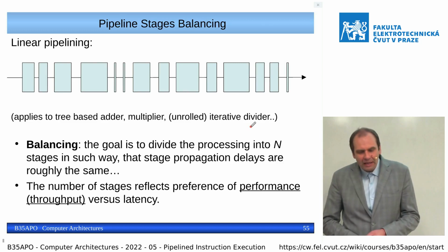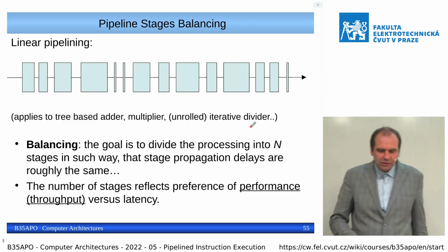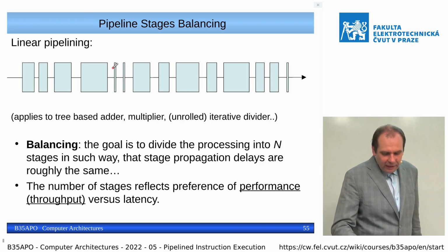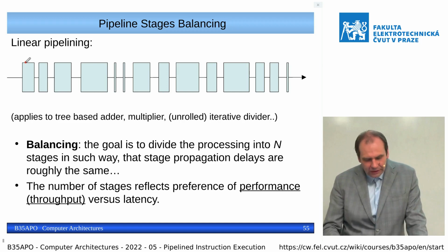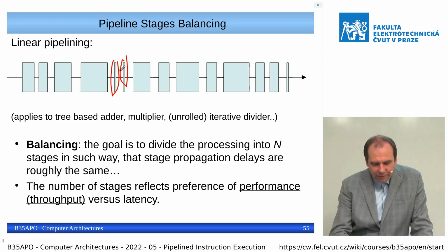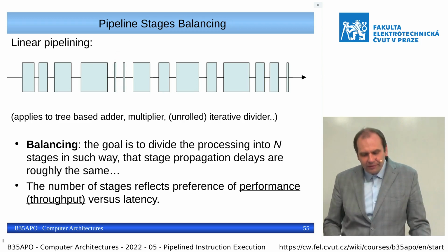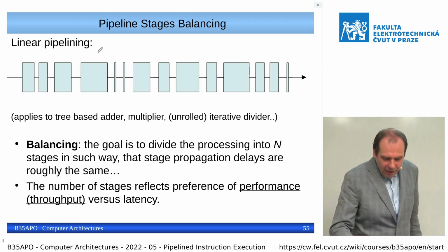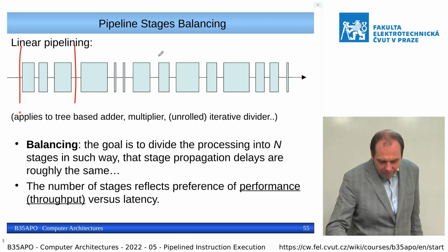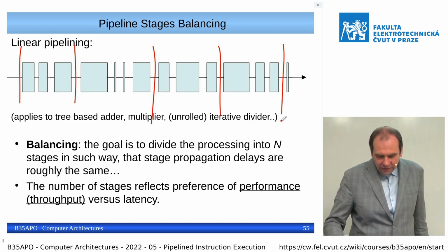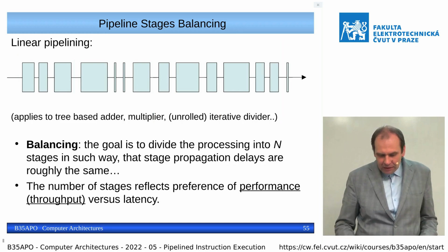And for the pipelines, if we want to speed up a processor more, then we want to divide the pipeline into more stages. But if we have a common clock cycle, which we usually have for all the stages, and some stages are processed very fast but we reserve for them a whole clock cycle, then we do not gain maximum throughput. So for this reason, we probably want to combine some stages together such a way that we have a pipeline balance.